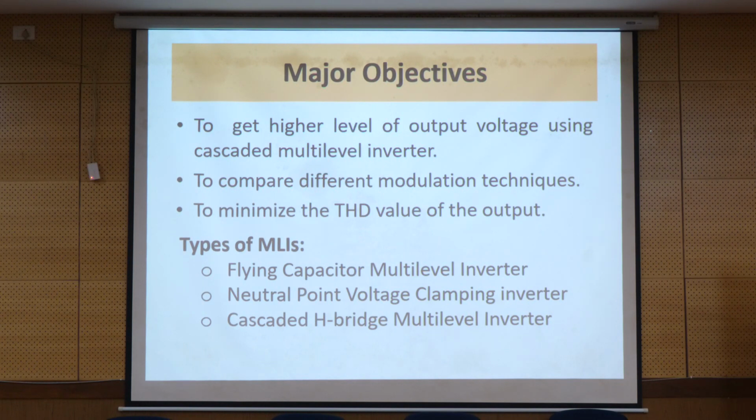My intention is that the 3-level diode clamped multi-level inverter itself is complex. If you go for a higher number of levels, the switching pattern is going to be much more complex. It is not repetitive. That is the reason it can be done modularly at lower levels, not at higher levels, up to the popular 3, 4, 5 levels. For academic purposes also, you can have 3, 4, 5 levels.